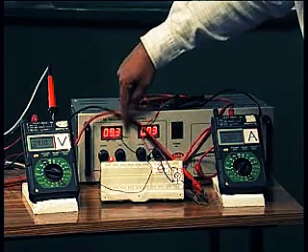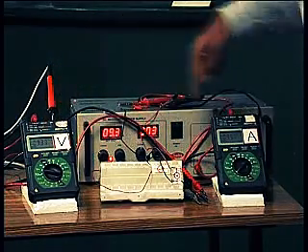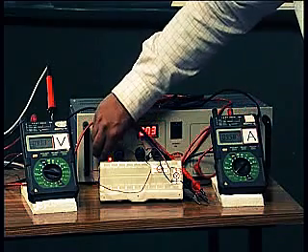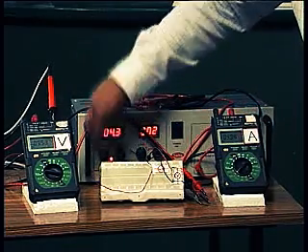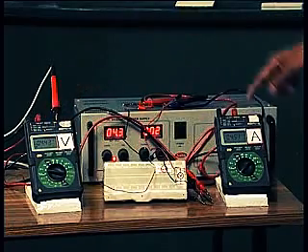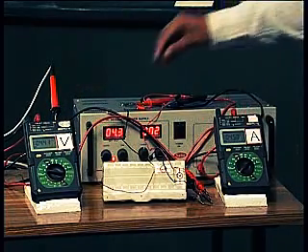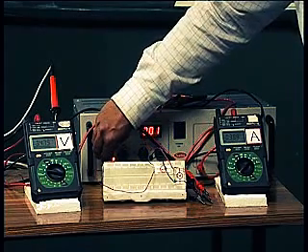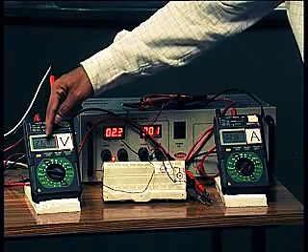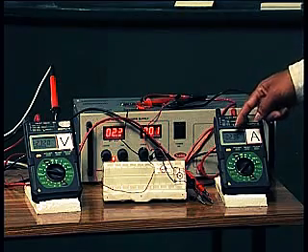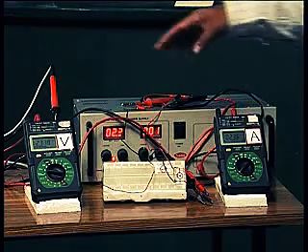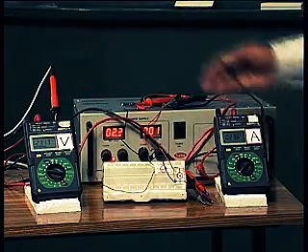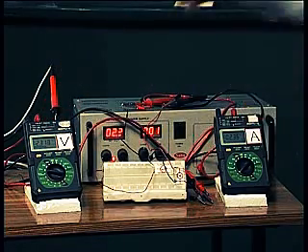So you can see the voltage is around 9 volts and the corresponding current is around 9.5 milliamps. If I reduce the voltage to some 4.4 volts, the current also is around 4.5 milliamperes. Now I decrease again to around 2 volts, 2.32, and you can see the current also is 2.36. Therefore you can see as I decrease the voltage, the current also decreases. When I increase the voltage, the current also increases.